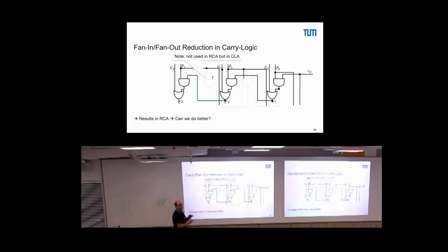So where are we now? I just left the gray part because we need it in a minute. Well, what we have here is AND or C1 fed in into AND or C2 fed in into AND or C3. That's just a ripple carry adder, right? So it's the same structure. By this transform, we have now converted it to a ripple carry adder.